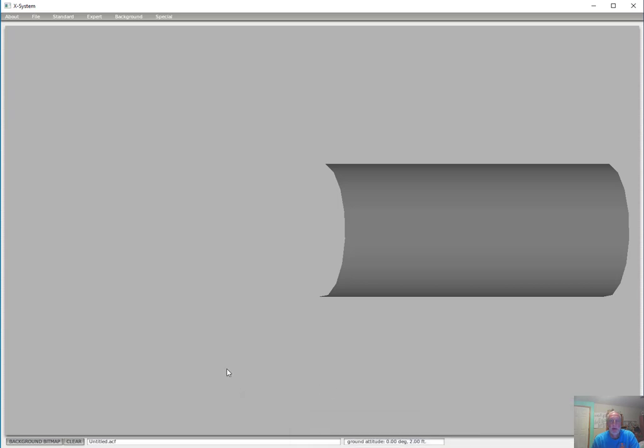Hello, this is part one of the tutorial on how to create our F4 airplane in Planemaker. I've launched Planemaker 9.0 and we're going to create the wing, the horizontal tail, the vertical tail, the weight and balance, and the control geometry menus. So the first thing we do is click on Standard, choose Wings.